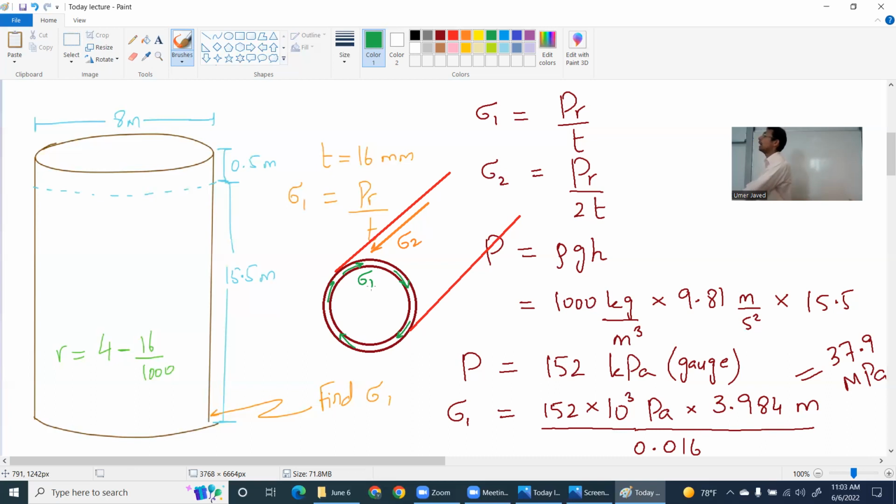But I stopped you there because you said you are going to ask us about principal stresses. These are already principal stresses, by the way. If I say stress 1 and stress 2 and there is no shear here, I'm talking about stresses that are themselves, in their totality, in their intrinsic sense, principal stresses.